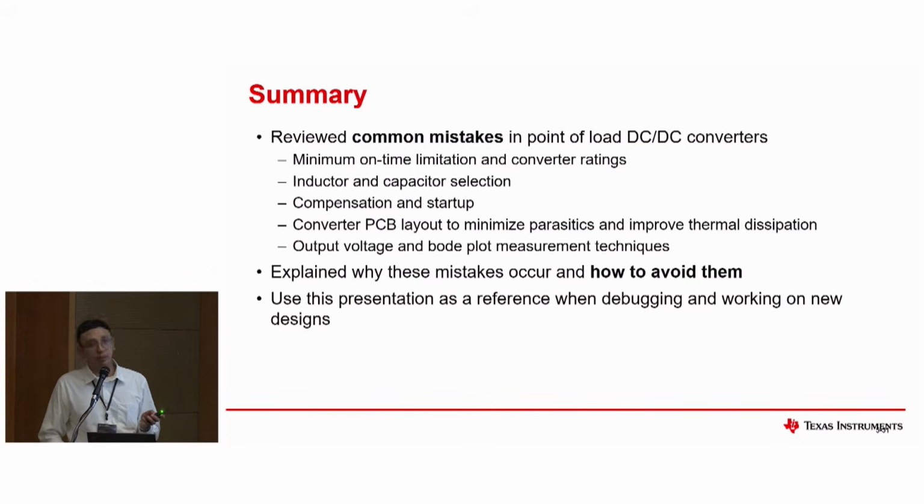Next, the inductor and capacitor selection is very critical. You have to ensure that the inductors and capacitors you select are enough to support the device. And then compensation and startup. And then converter PCB layout to minimize parasitics and improve thermal dissipation in your design. And then output voltage and Bode plot measurement techniques. We did explain why these mistakes occur and how to avoid them. Hopefully you could use this presentation as a reference when debugging and working on your new designs.